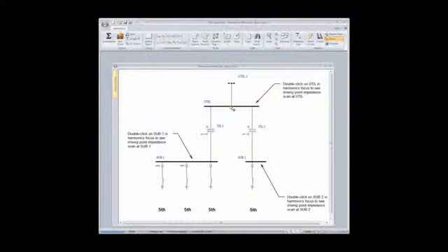And when I did my grunt work underneath him and I was cutting my teeth, he would tell the story of a utility applying a large fifth harmonic filter at a point in their grid because they had this issue and they wanted to kind of shunt off some of that fifth harmonic current. So they designed it. They designed what size the capacitors and the reactors would be for that filter. They put the thing online and it quickly exploded. And the reason why it exploded was very simple: it absorbed every fifth harmonic current on the whole utility grid for around 100 or 200 miles.